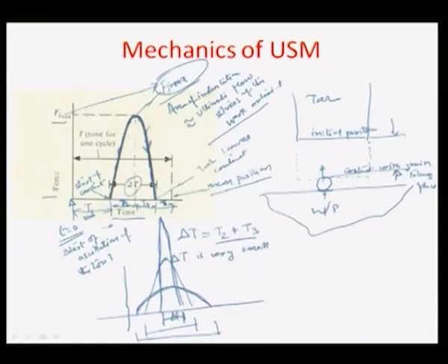Therefore, if we look at the average force, it can really be a time averaged force, meaning that if the time period for the vibrating tool head is capital T, then the average force can be written down as the integral from 0 to T of Fi as a function of time, dt, divided by capital T.